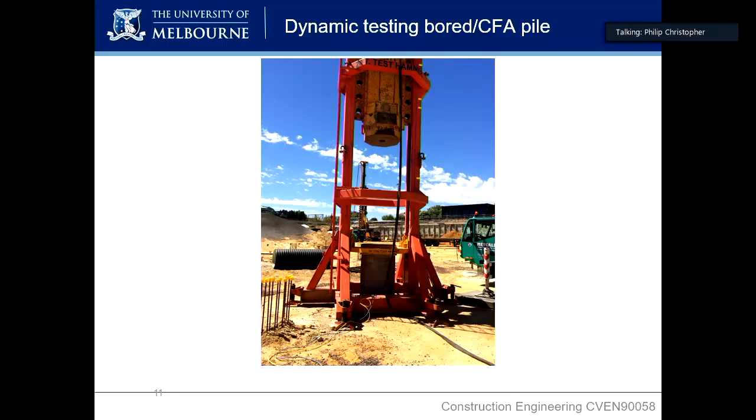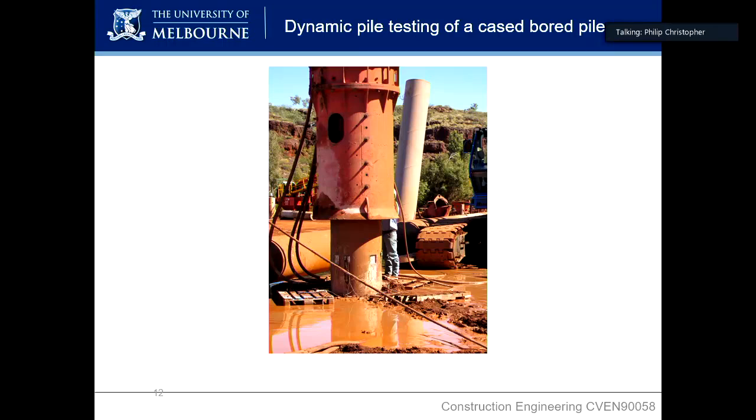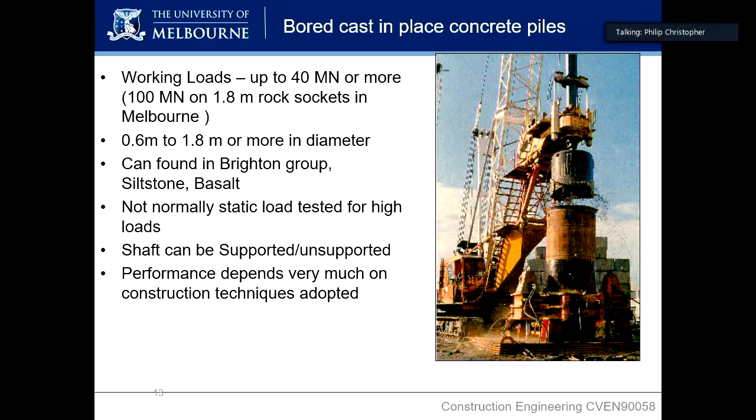So it might be something you specify in your task: yes, let's test 5% of piles. You will then use that factor to calculate your phi-g. Here's another example, this one's testing a cast bored pile, for example, but the concept's exactly the same.